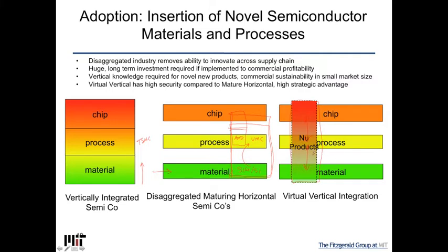But of course, the thing that really took off was that at the time, at 90 nanometers, Moore's law had ended. Now, this wasn't public knowledge, but most of the advanced places like AMD and Intel had already made 90 nanometers and saw that the current wasn't high enough. So where we wanted to build innovation and create new, drastically different things using the same fab, people still just said, well, if I've got this problem, I just want to use it to make my regular MOSFETs better, and with that extra boost I'm getting, that'll allow me to continue on Moore's law. So again, another shift where we had been looking at applications that were to use the same fabrication facilities and do something drastically new at the product space, but in fact it was pulled in and used for Moore's law.